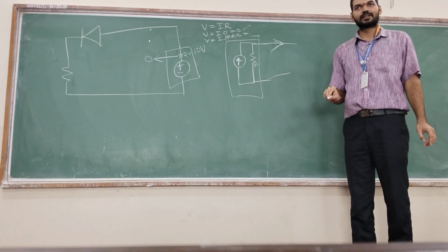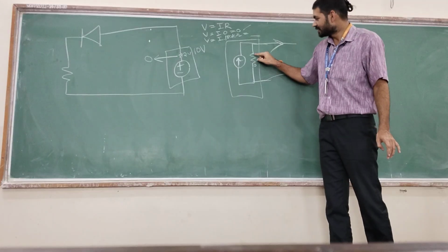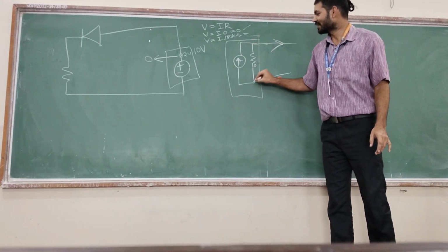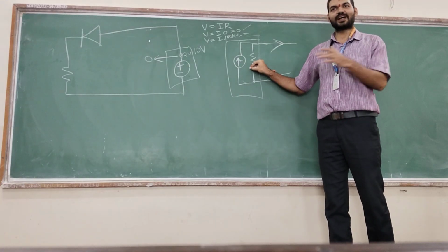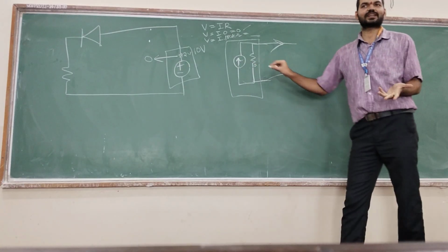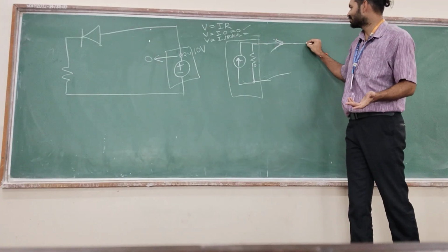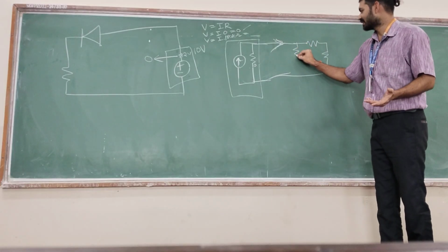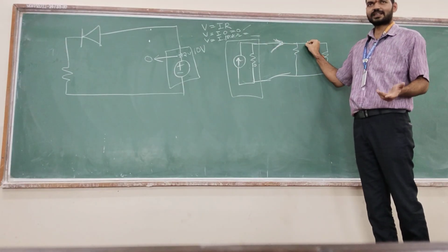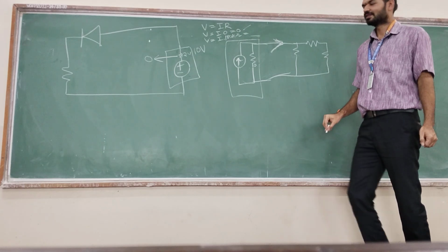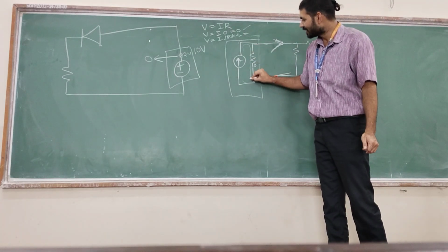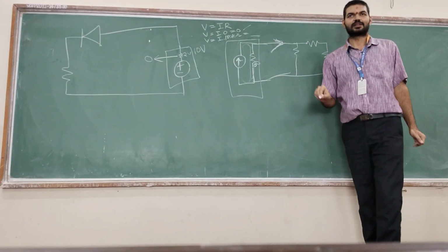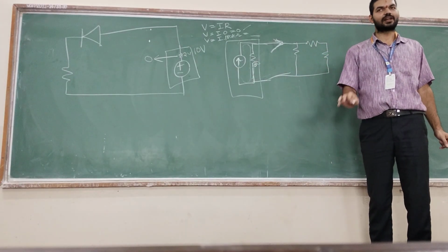Why, tell me? Suppose they ask, what if this is made 0? If this is made 0, the current comes like this, doesn't go outside, goes here and sits here itself. No use making a current source. What is the use of this current source if it is not giving the current outside to outer circuits? There is a circuit ahead. Okay, if the current doesn't come outside, what is the use? So current should not rotate in this loop. Therefore, this should be infinite, ideally, practically very large.